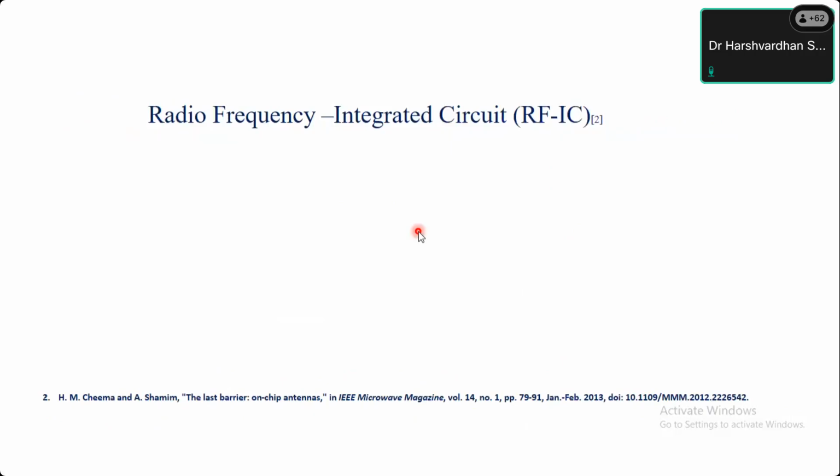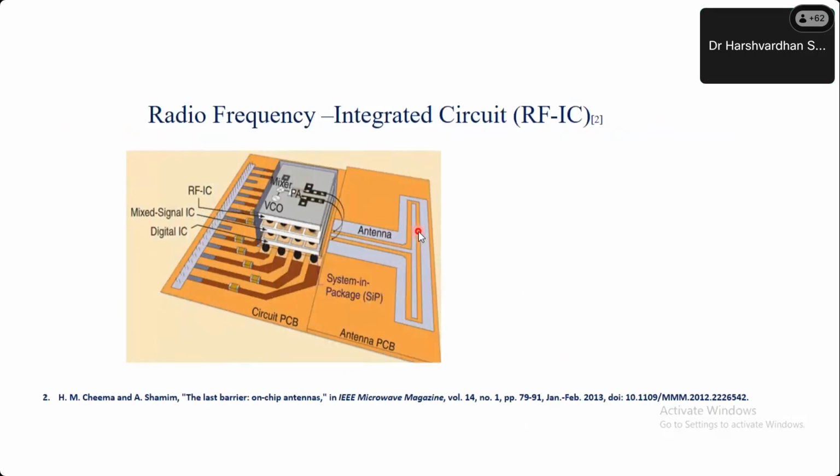If you see here, inside that RFIC, just now what we have seen, there are different components like the RF front end, everyone knows. So there are mixer, power amplifier, voltage controlled oscillator, all those things in the RF front end system. Now, if you see here, in this RFIC, in a single front end, the antenna should also be there, right? This IC is here, but the antenna is kept here outside, on the PCB, or you can say outside of the IC, right?